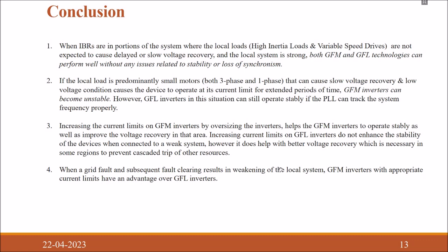Second, if the local load is predominantly small motors or has low inertia, then the voltage recovery will take time. GFMs, if their current limit is hit, will become unstable, and GFL will only work as long as the PLL can track the system frequency properly. However, if we increase the current limits of GFM by oversizing the inverters, GFM can also operate stably, and it will improve the voltage recovery in that area.